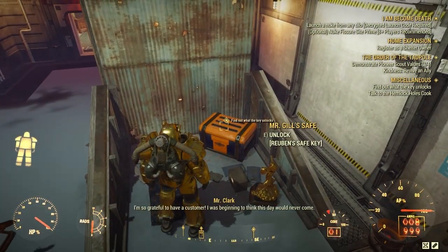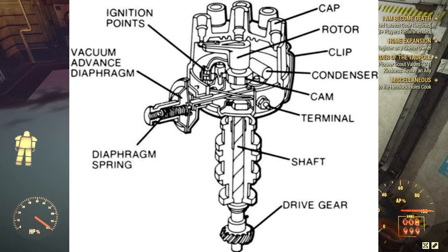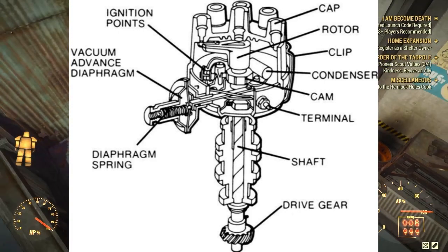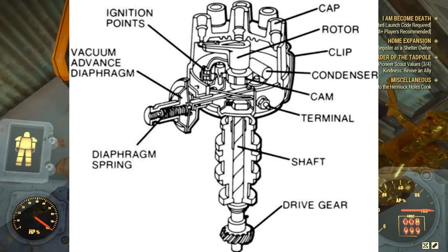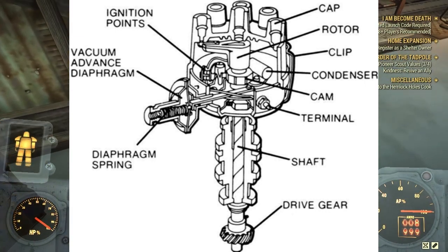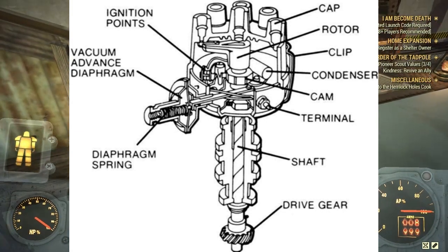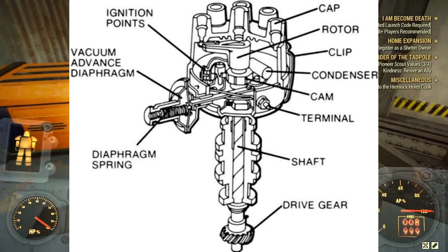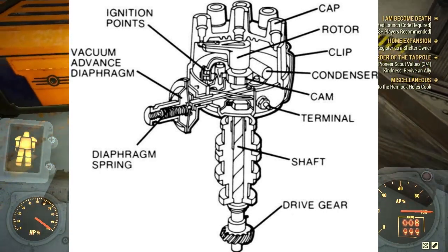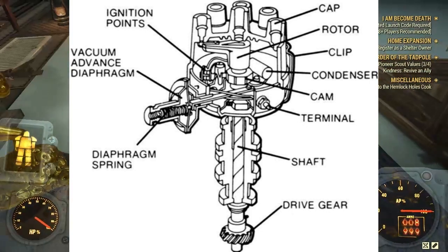What a distributor was, and what it technically still is, because they are technically still around due to older vehicles, is a mechanical component that would read off of the camshaft and would basically say, hey, where are you at in the spinning cycle? And you would usually be able to adjust them.